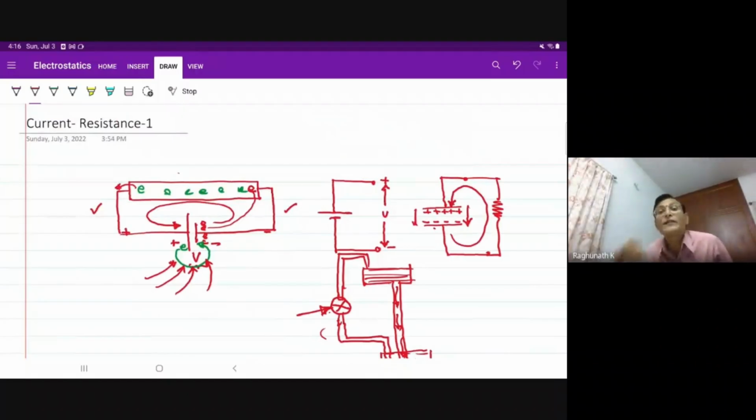And in transients, we will see that after some time, the current through this resistance becomes equal to 0. It exponentially decreases at the rate given by the time constant, RC. Because there is only passive resistance connected between, there is no energy supplied to the capacitor here. So energy is stored in it.